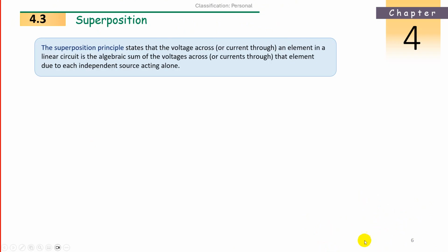Second step, remove the first voltage source and start with the second voltage source, remove all other voltage sources and calculate all the required branch currents and branch voltages. Like this for the third and fourth voltage source. However many voltage sources you have, that many times we analyze the circuit, each time acting with one source only.